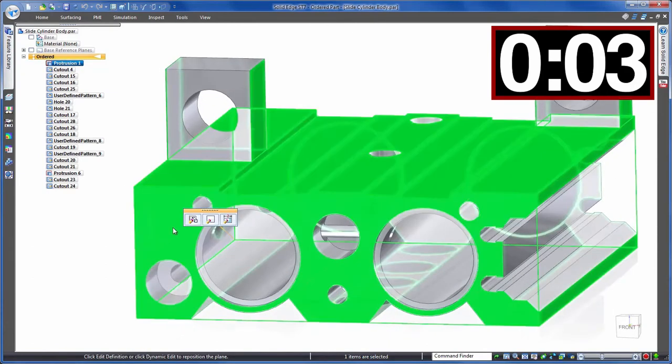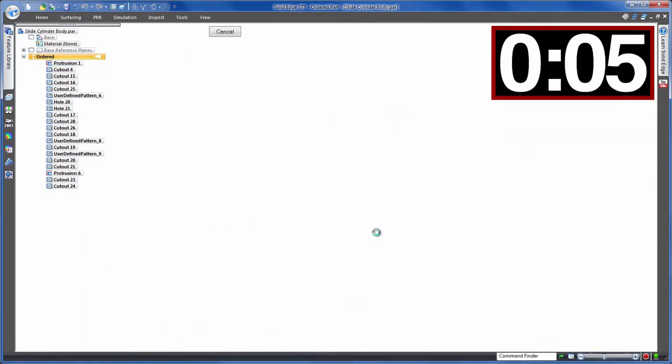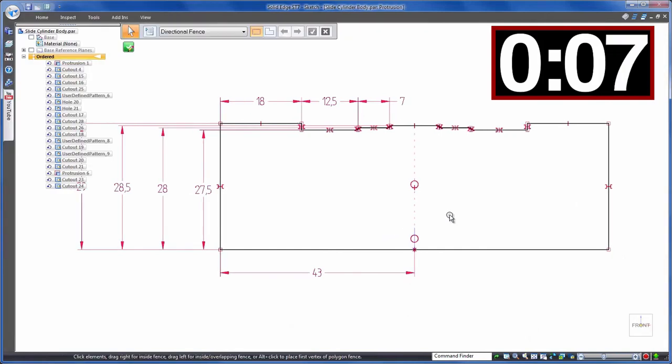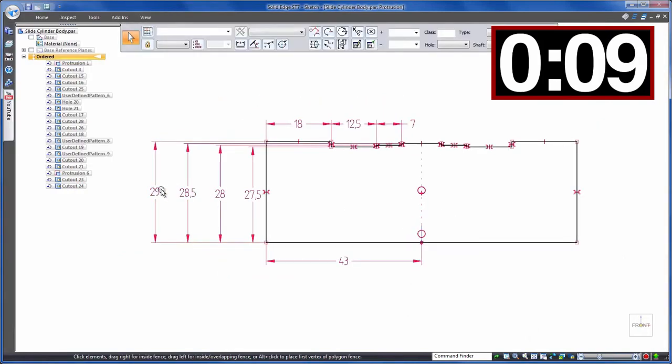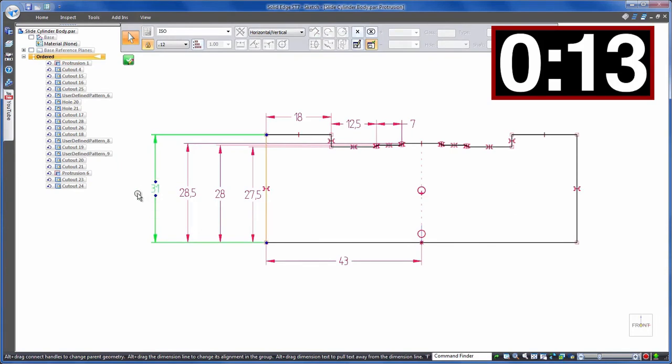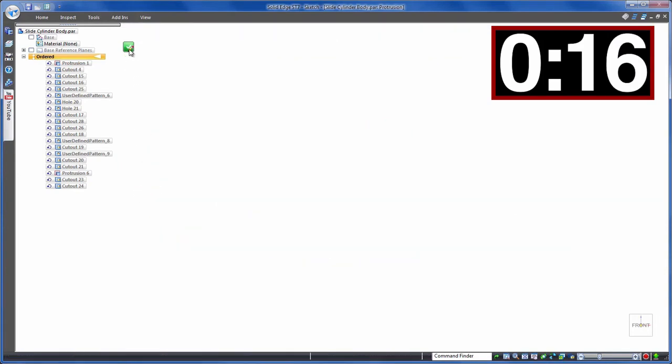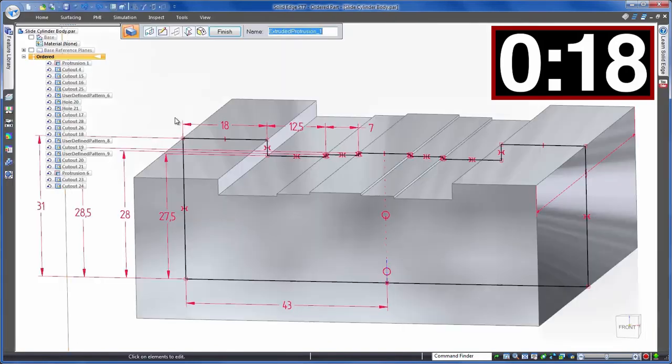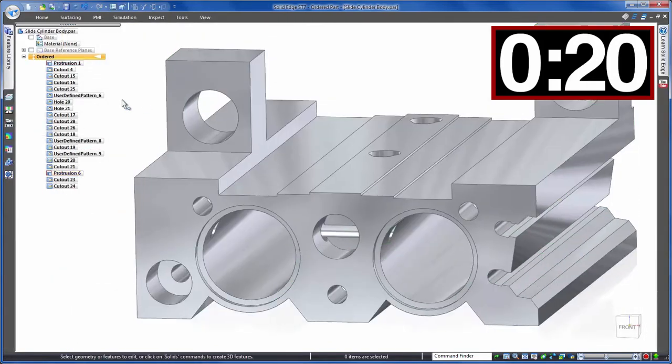So for the first edit, we click on the model to edit the sketch of the highlighted feature, assuming this is the correct feature. Luckily it is, and we're also lucky that we have a fully defined sketch with a dimension of the geometry that we need to change. We'll change this to 31mm as required, the sketch is updated as we'd expect, and then rebuild the model.